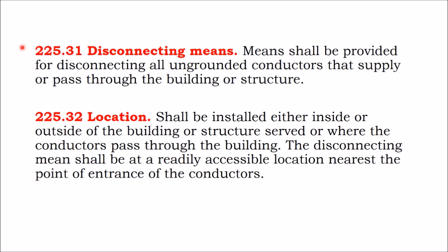I suppose the knife switch is something that can be viewable from a distance, and you can open up and inspect the disconnect switch and see that the knife switch works. I guess a breaker could fail. But code only requires breakers to serve as disconnecting means, and your utility may or may not require a knife switch disconnect to complement the breaker on your electric service panel.